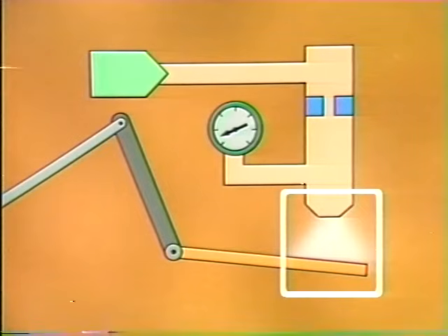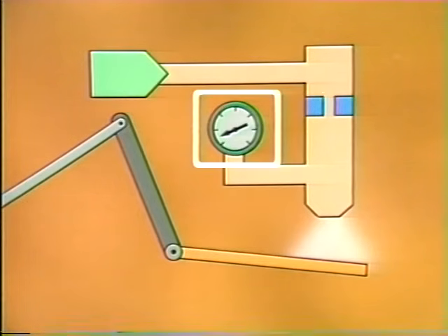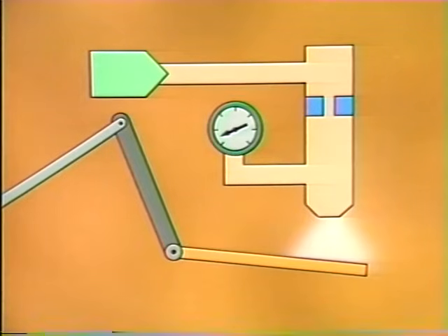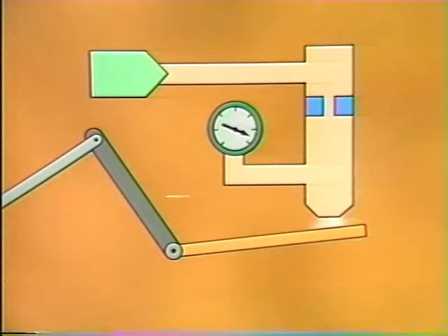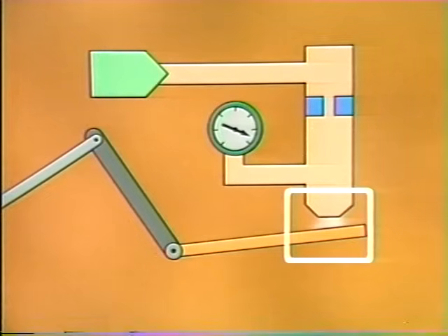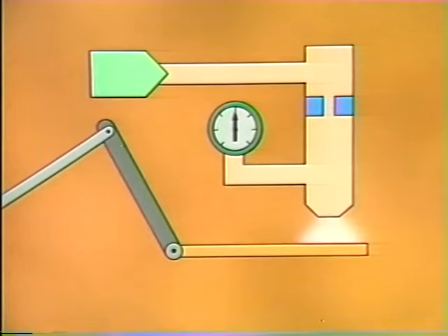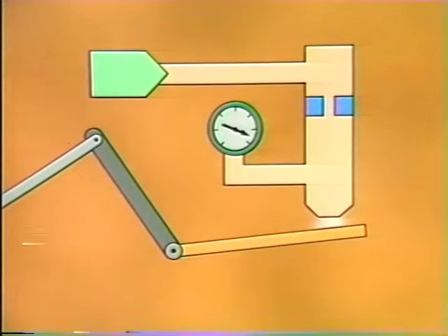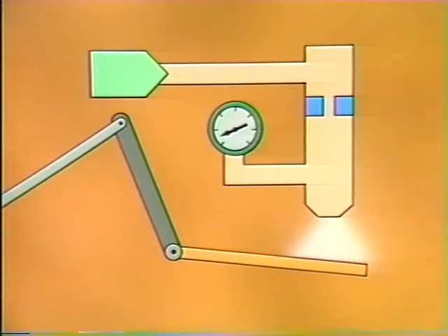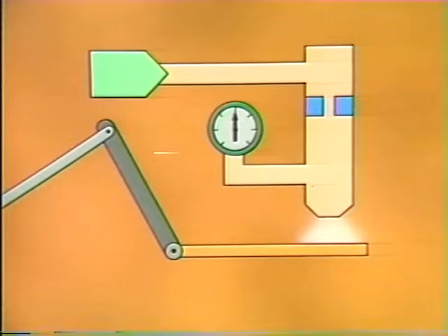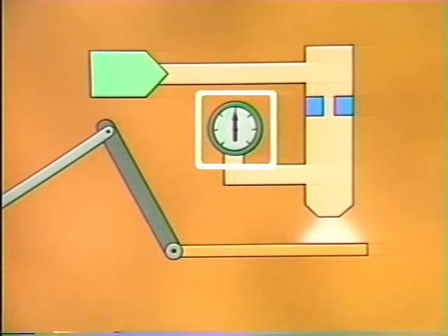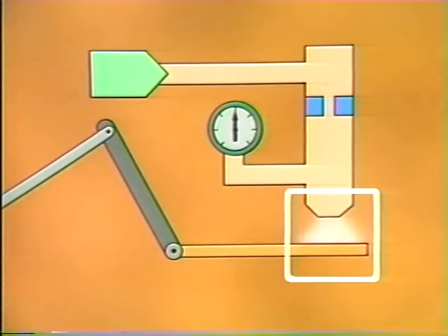This would allow air to flow almost unrestricted from the nozzle, resulting in a decrease in back pressure. On the other hand, the flapper could be positioned close to the nozzle. This would reduce the flow of air from the nozzle, increasing the back pressure. Each time the flapper is positioned, whether it covers or uncovers the nozzle or any position in between, it results in a back pressure that is nearly proportional to the distance of the flapper from the nozzle.